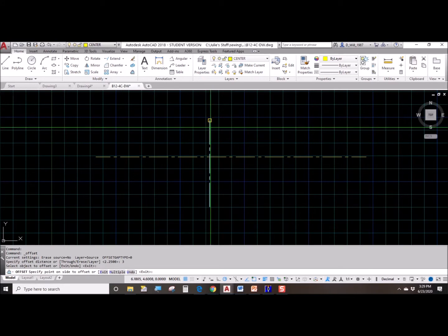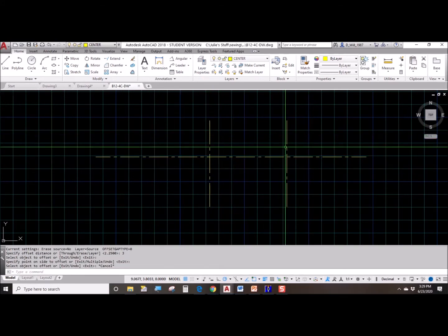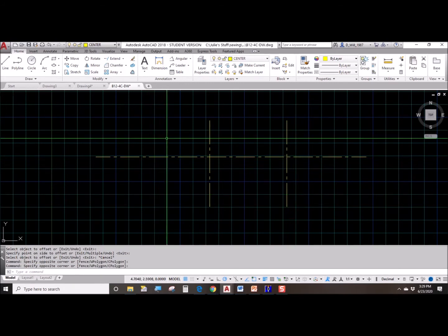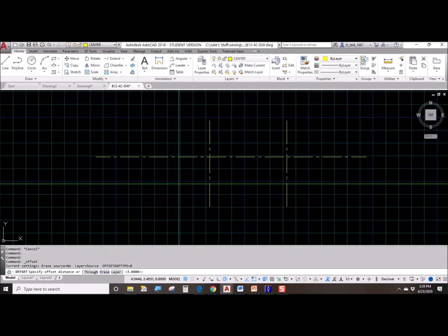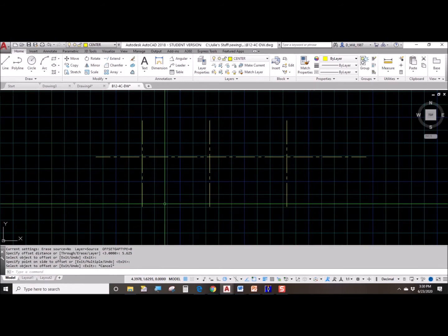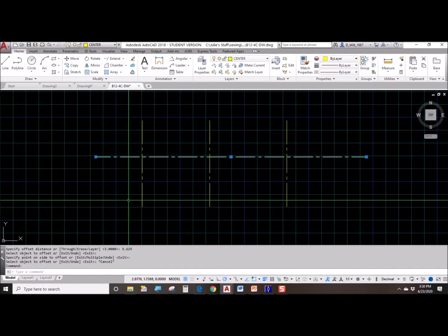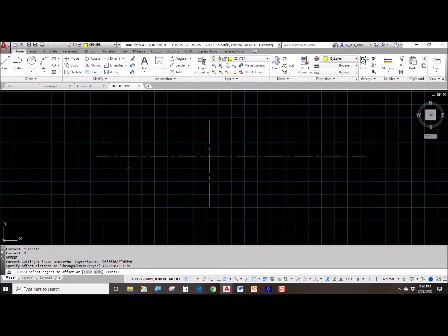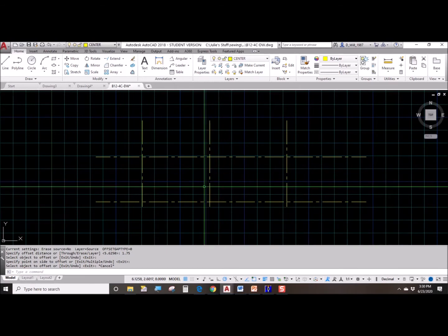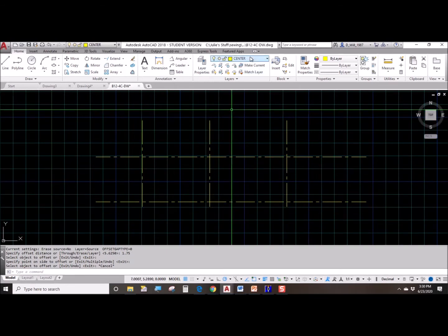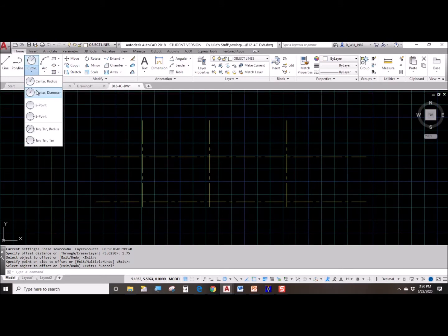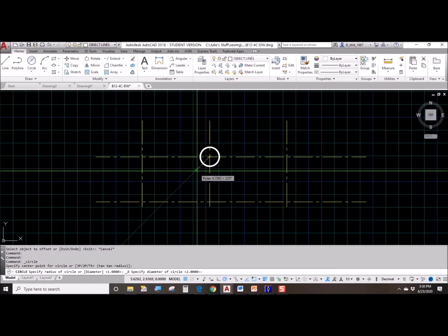And then from the little circle on the right to the other little circle down here, there's an offset distance of 5.625. And there's a distance from the center down to here of 1.75. Okay, so that little bit of framework there will get us started. We'll do object lines. We'll set up our first circle. It's a large circle with a 3-inch diameter.